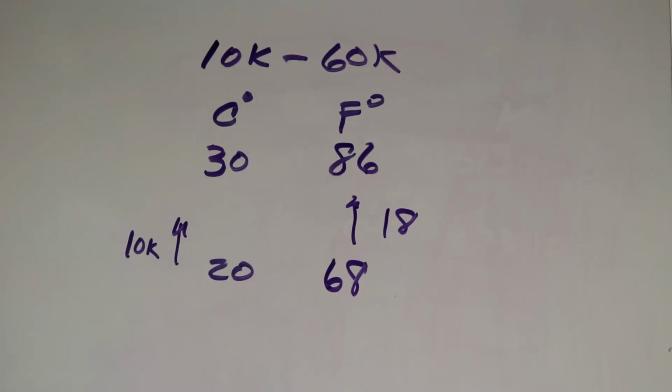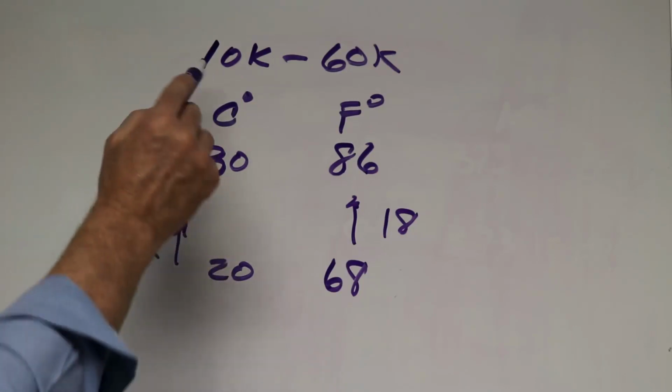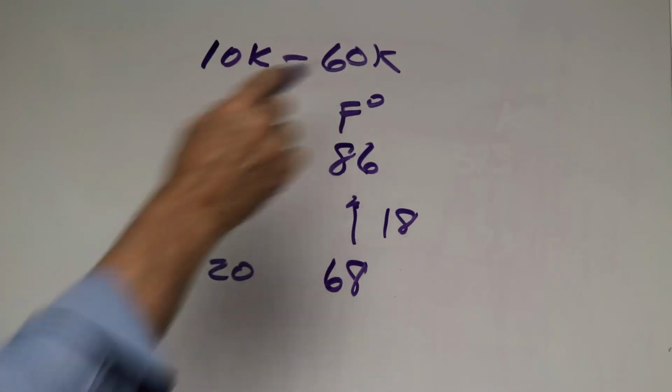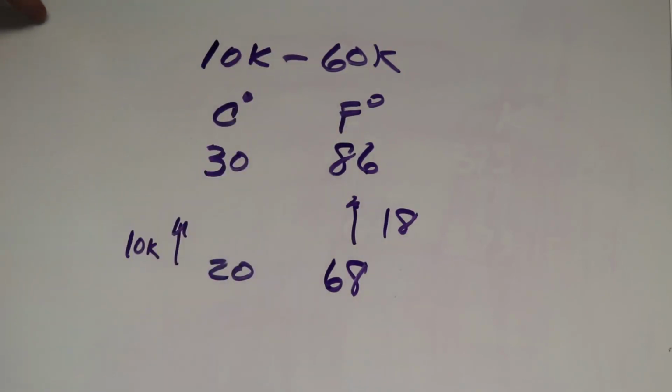Okay, so in the instructions, when it tells you to go from 10K up to 60, this is how you can program. So if I want to take the most sensitive level at 10, when we went into the controller, we saw that it was going between a 4 and a 5. So let's say my 5 was the differential. So it looked at the temperature differential and it said that that differential was 5.